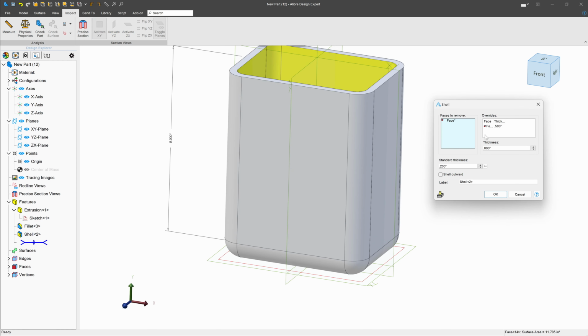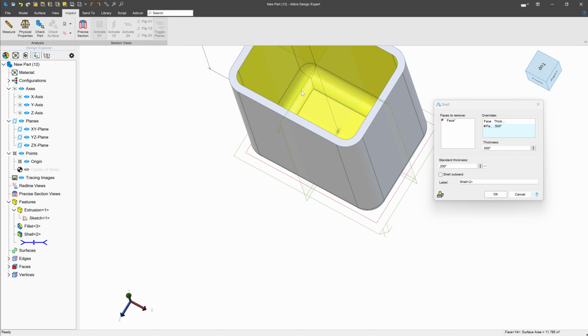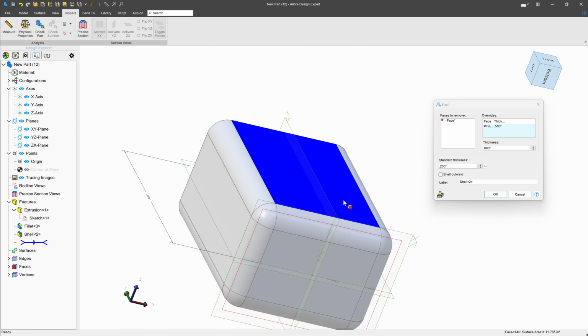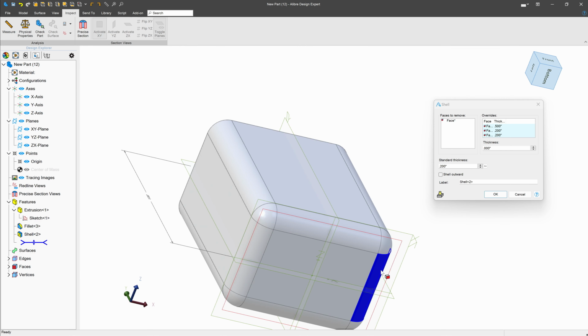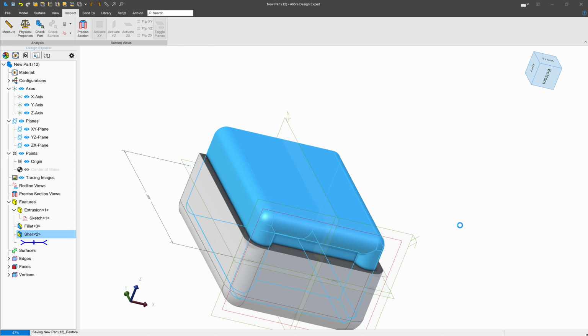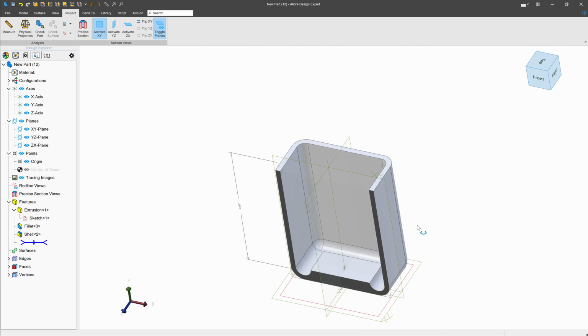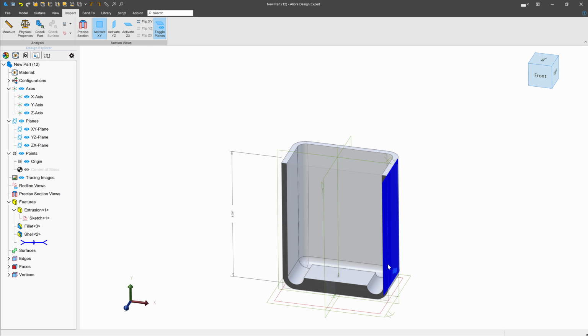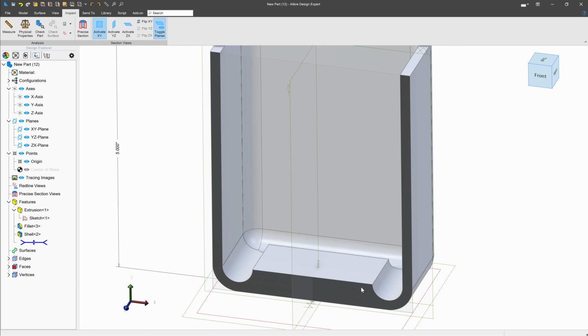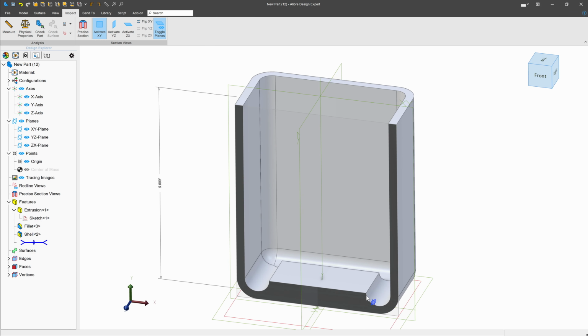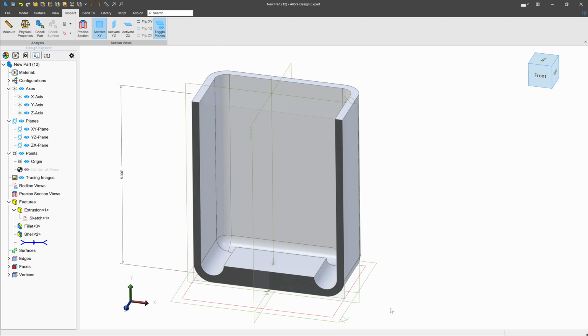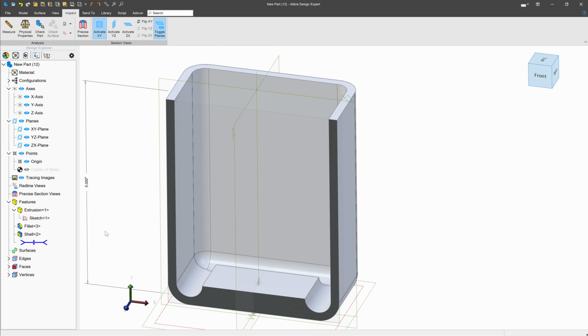So I can go to Edit. I can add some more faces in my various radius shell, right? Maybe I'll add these curves and see what that looks like. And look at that. We're messed up, so we're not even going to be able to do a constant or a various thickness in that situation. So be careful how you apply this various thickness tool so that you end up with something that you intend. But it is very, very handy to be able to shell something out hollow.